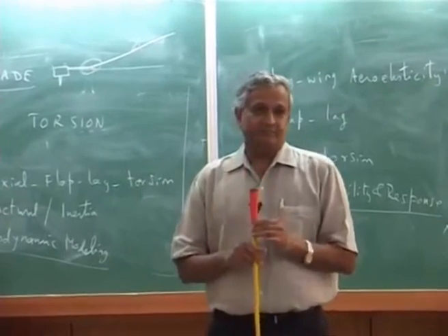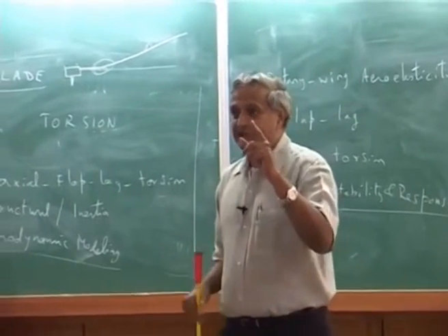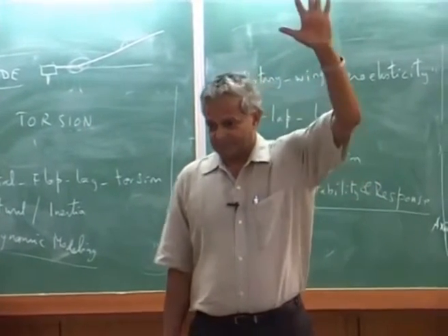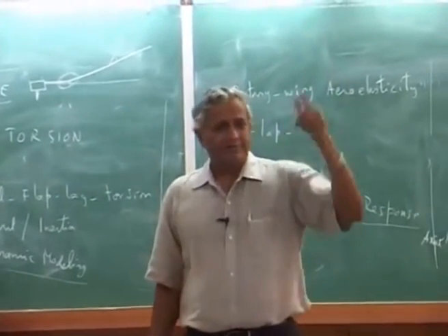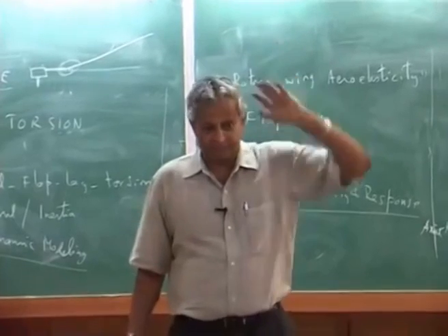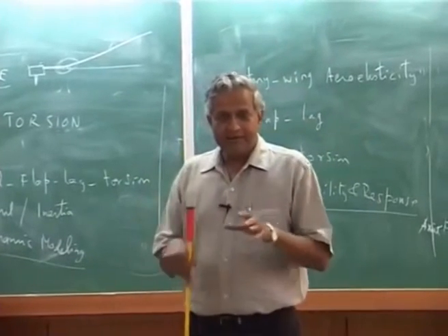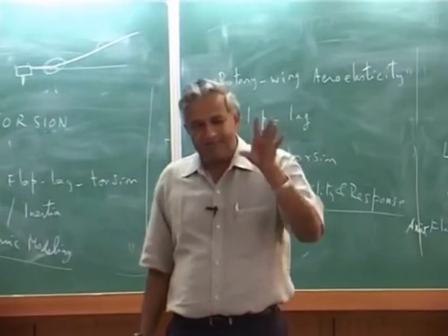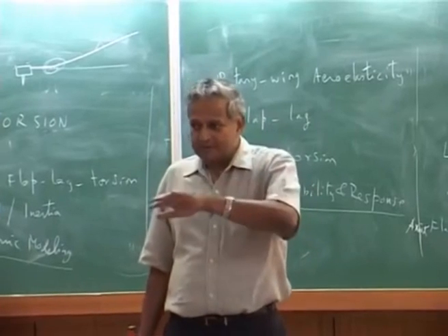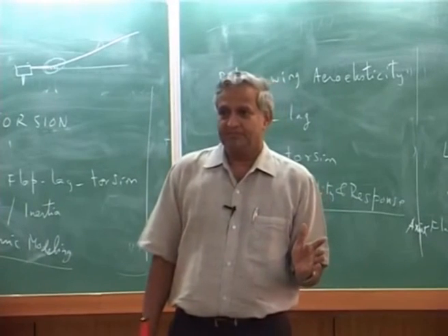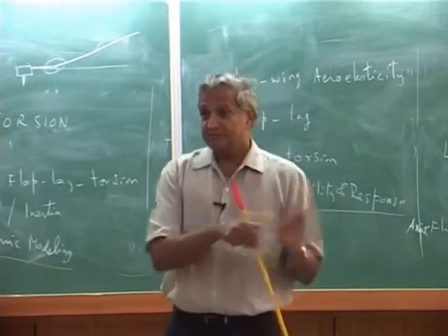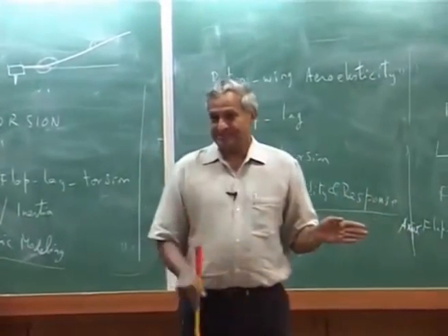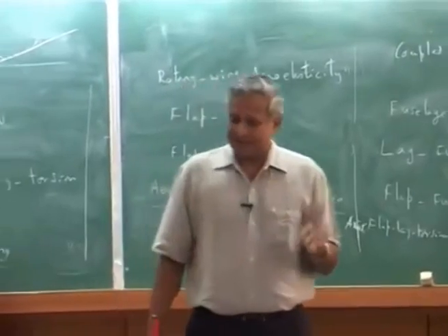Then there is something like, hey, let me not look at individual blade. I will start looking at this as a rotor disc. I don't worry about the individual blade. I'll see how the disc is moving. Now again, in the flap motion, how the disc will move. In the lead lag motion, similar thing. That is where, from a rotating frame to a non-rotating frame, some transformations one needs to make if you want to analyze certain stability problems. Otherwise it becomes a little messier, complicated.